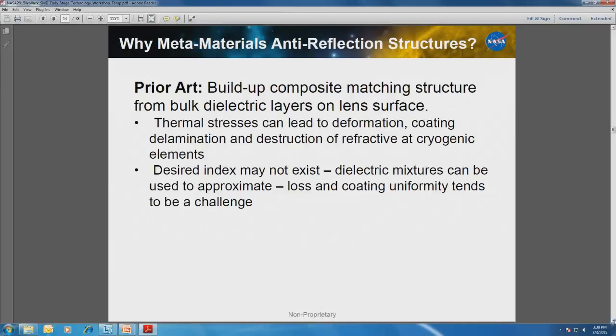Okay, so one of the problems which we'd like to solve is we want to have many detectors. We want to make a very large field of view instrument, with many detectors looking at the sky simultaneously. Since we all have computers, large chunks of silicon are readily available, more or less industrially. You can get a 30-centimeter piece of silicon, and that's a reasonable material to make a lens out of in the far infrared. And the traditional way of making an AR coating is you essentially glue a material or layers of material and make a composite material.